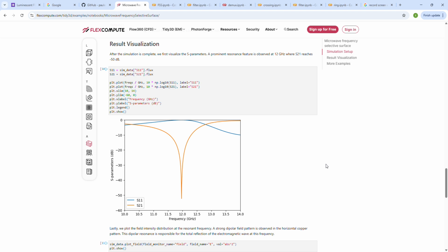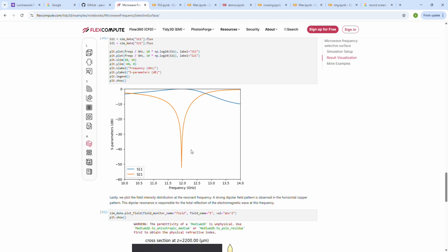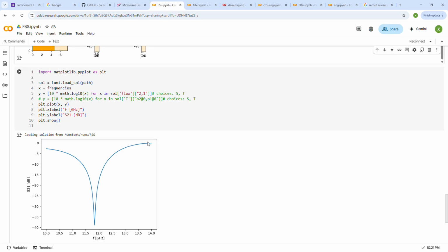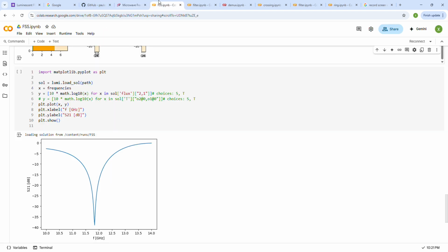That's not bad since we're using like 1000x less computational resource than them. The attenuation at 10 gigahertz and lack thereof at 14 gigahertz, those two values match almost exactly. Though the 10 dB bandwidth, I think theirs is a bit tighter than ours.